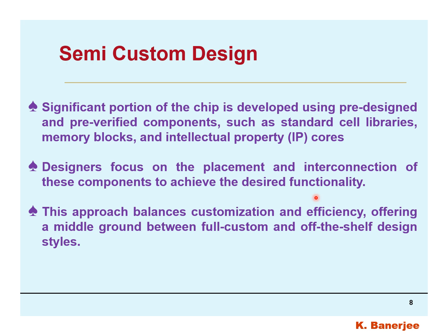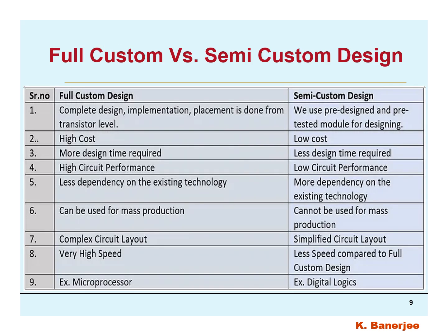on the chip. There will be some cell libraries. So it is classified into standard cell or macro cell or gate array. These are the divisions. So we have some pre-designed and pre-verified libraries which are designed using the fixed designing. And here we have finally reached the difference between full custom and semi-custom design.